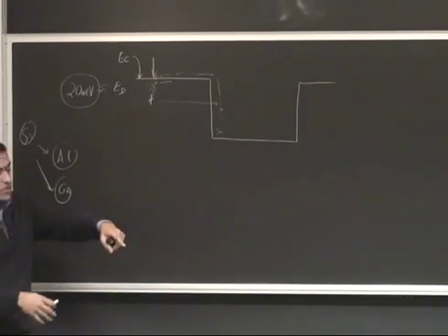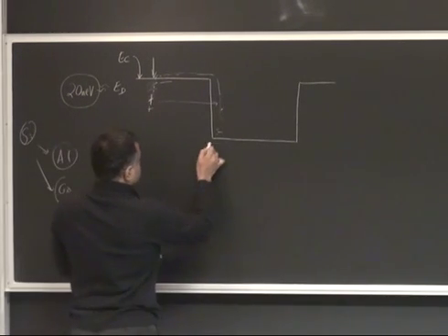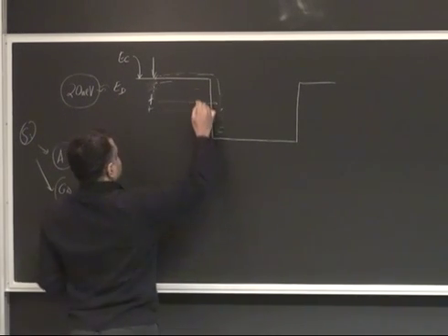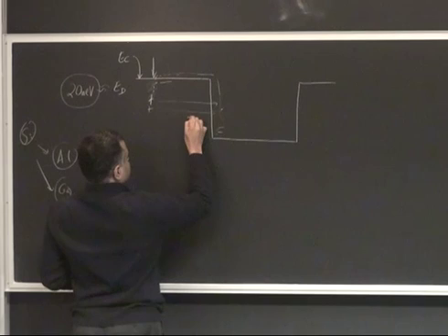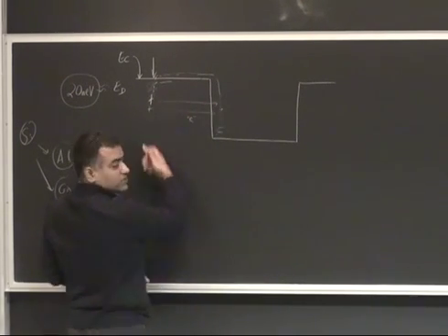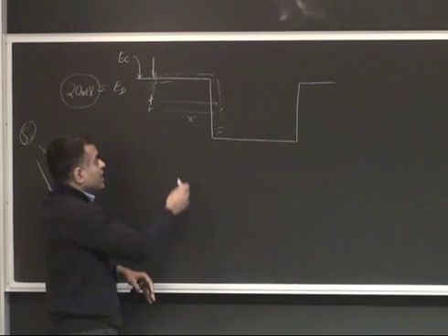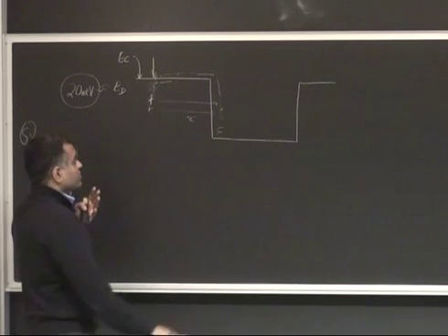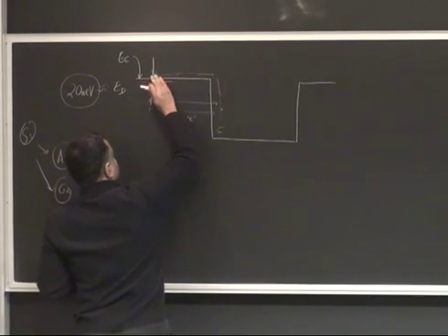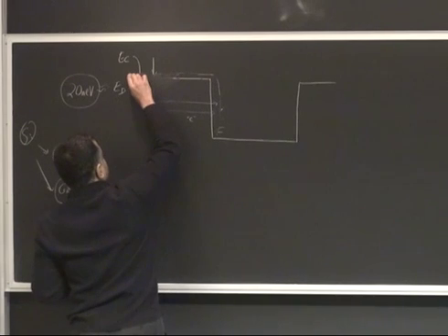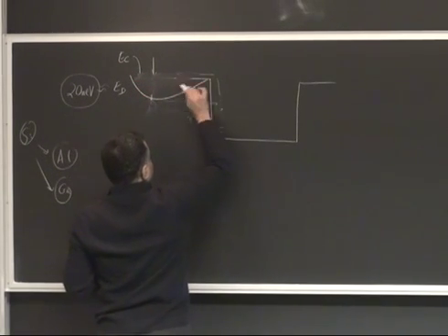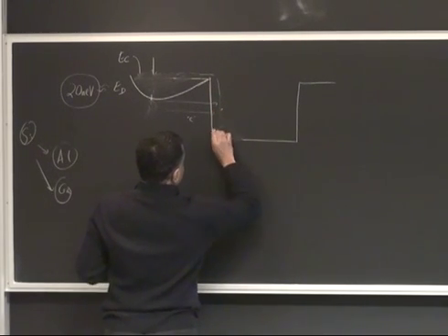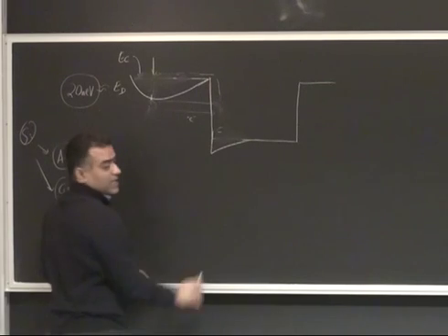As this happens, so you dope even more, and you put more dopants here, more electrons here, and then the field goes up. So when the field is pointing to the right, you can see that whenever the field is pointing to the right, I release a negatively charged electron here. It wants to move to the left, right? And so what does it say about the band diagram? It says that the band is bending now because there's a field, right? And so what's going to happen now is as you dope it more and more, this band here is going to kind of bend like this, and the other thing is the field will be continuous across the junction, and it's kind of going to start looking like that.